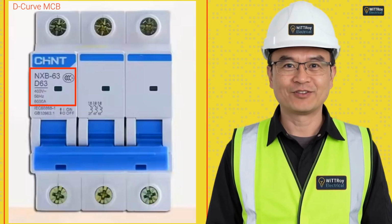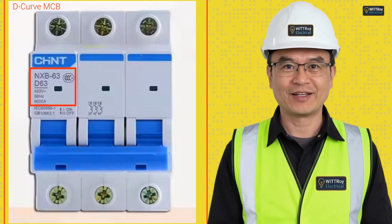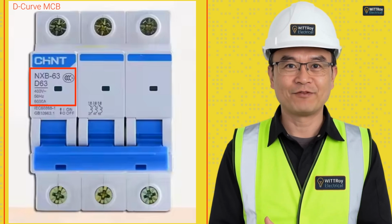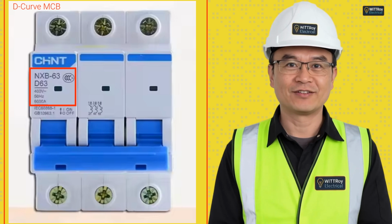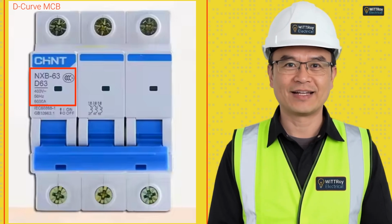Let's look at this device. First, I check the label. I can see D63. That means it is a D-curve 63 amp device. This is a D-curve MCB. I can see 400 volt AC and 50 Hertz. This means it is rated for 400 volt AC 50 Hertz.